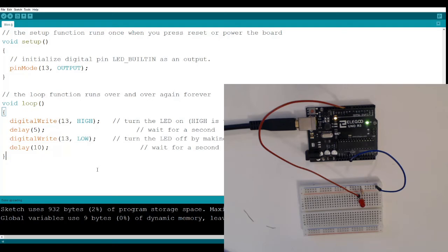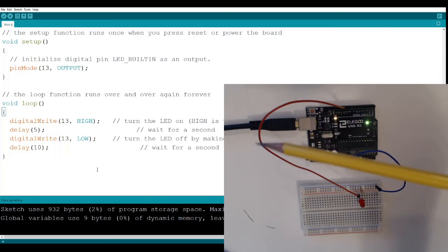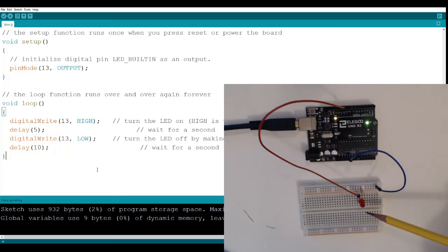That's our return terminal. So conventional current will flow from channel 10 through the wire, through the LED, through the resistor, and then back to ground, just like in our basic circuits that we've done with batteries.